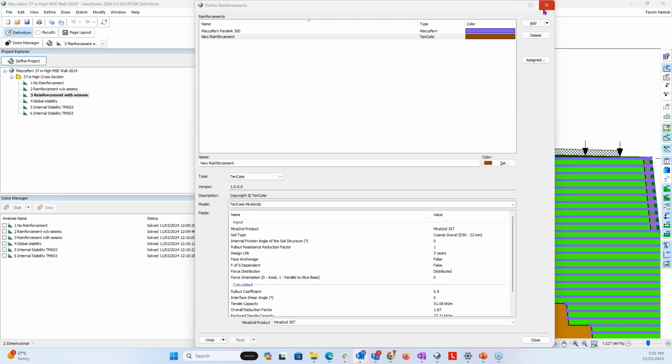So you can do it for the worst case scenario and the best case scenario. Your piezometric surfaces are going to be updated, and you can incorporate only the last analysis time, because you can run it as a transient analysis or a steady state analysis. You can only use the last analysis time, or you can include all the time steps and calculate the slope stability and the factor of safety for each time step of the rainfall.